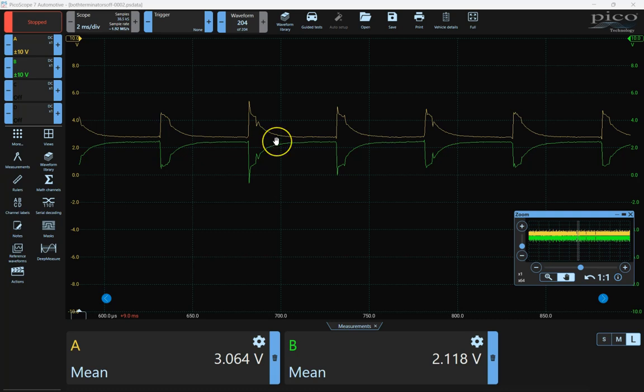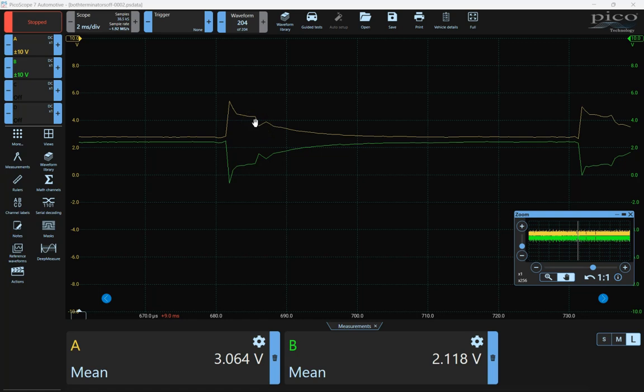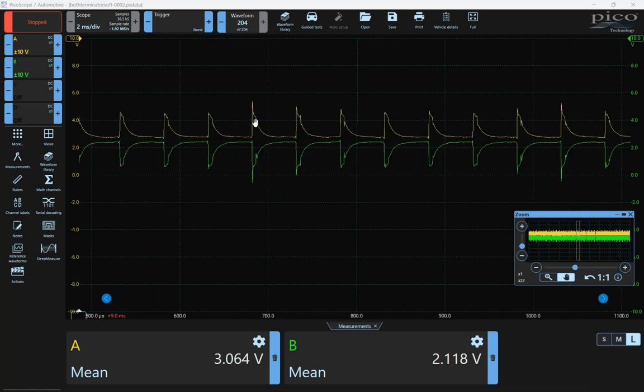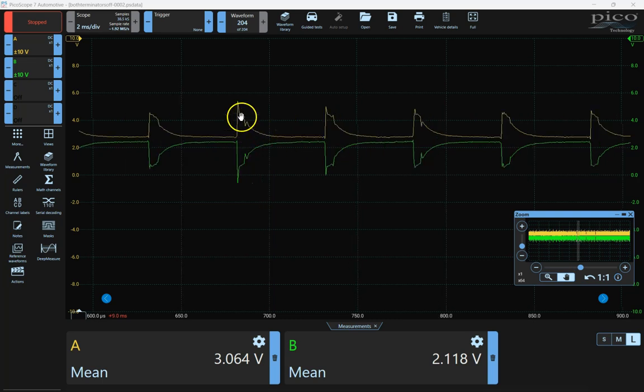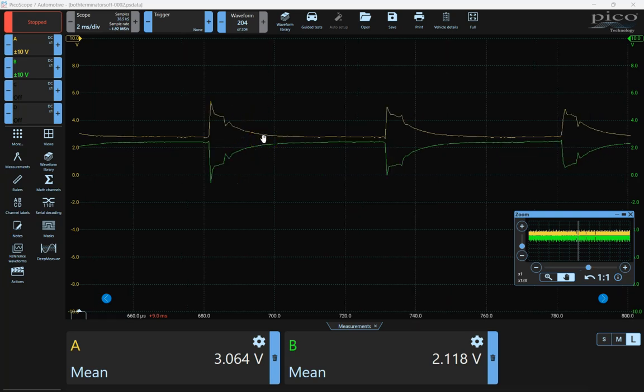this network. We can see that the wiring harness and the devices have this decay, this time for a decay. So it's trying to drive up to a dominant bit, and because it thinks that other devices on the network are more important, it stops communicating. The reason for that is this decay. The time for this to occur is too long. We cannot pull CAN high and CAN low back to the recessive state fast enough to be counted correctly